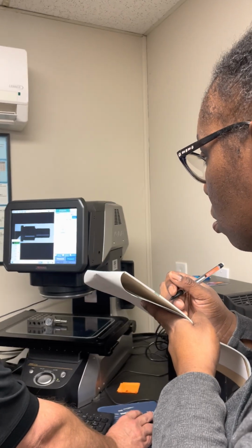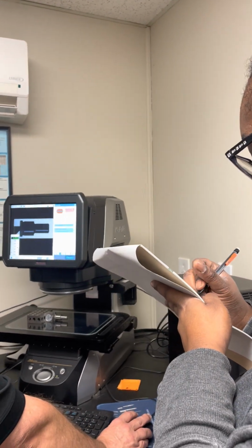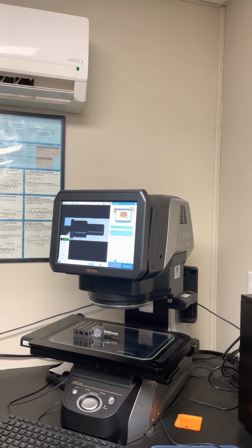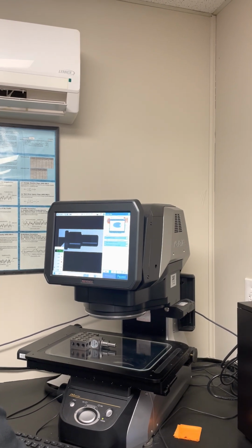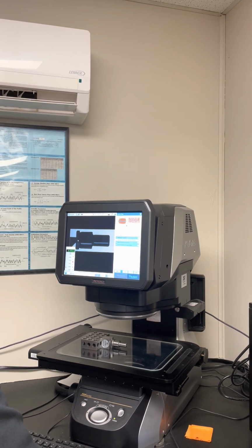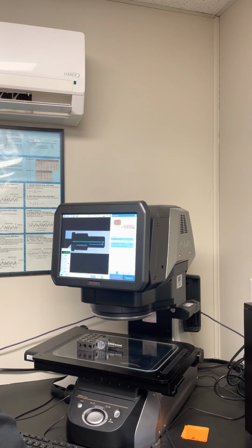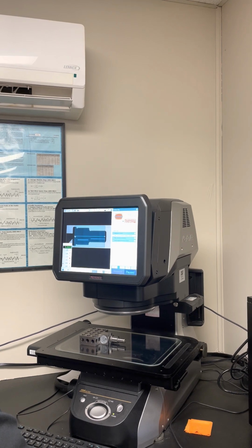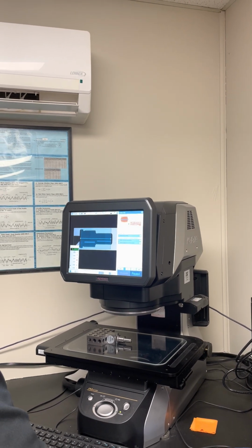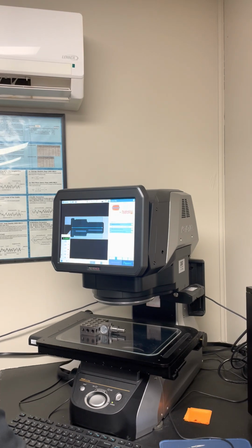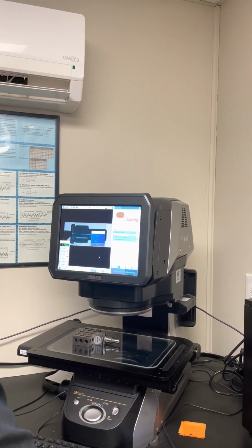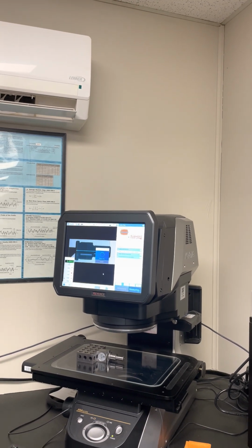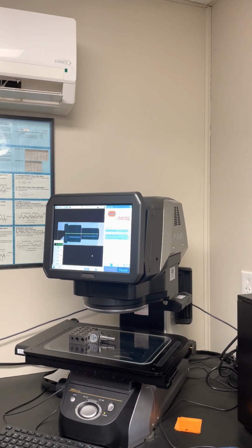So what I'm going to do is click center line. All of our operations have a tutorial, so if you don't know how to do it, you click the tutorial. It tells you to take 2 points and then spread it out. So I'm going to take a point here and a point here. Open it up. You don't have to take it to the very ends, but we're going to take a little bit farther. That's good. Now I'm going to hit apply. And that created my center line.